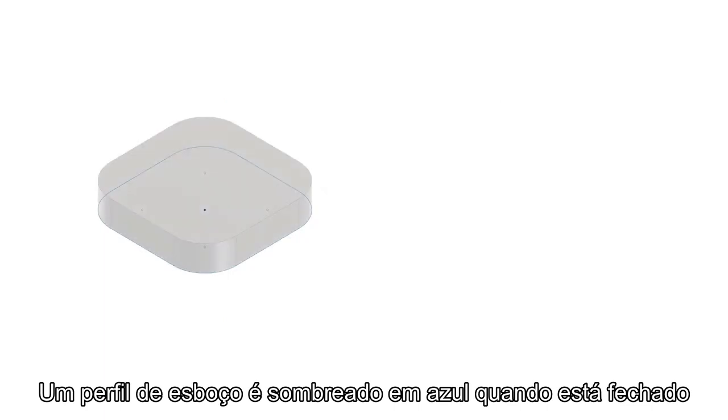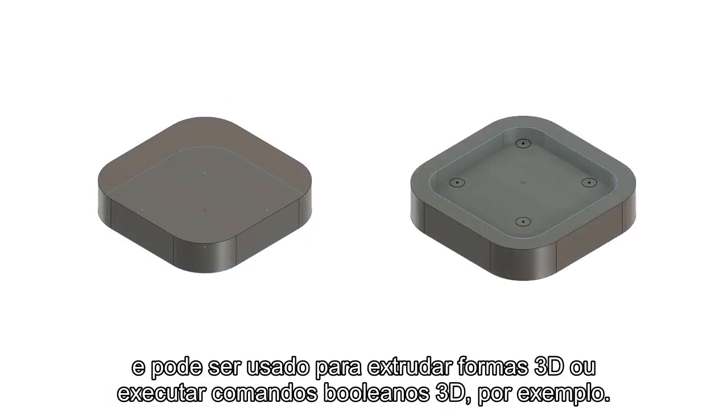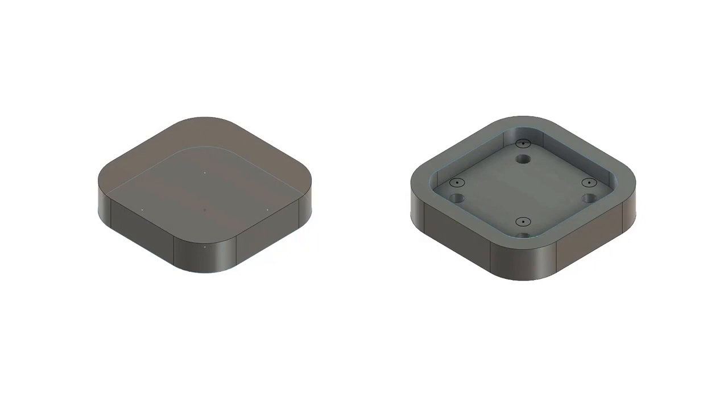A closed profile is a series of connected 2D geometry that does form a closed boundary. A sketch profile is shaded blue when it is closed, and can be used to extrude 3D shapes or perform 3D Boolean commands, for example.